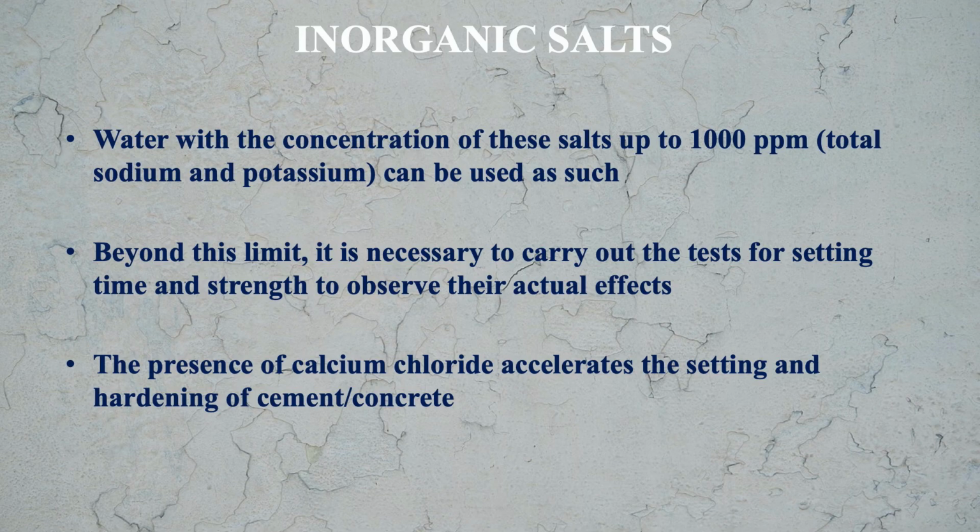The presence of calcium chloride accelerates the setting time and hardening of cement or concrete. So here you see the effect of calcium chloride: it accelerates the setting. Means when it accelerates the setting, setting time reduces, because setting is now happening at a faster rate.